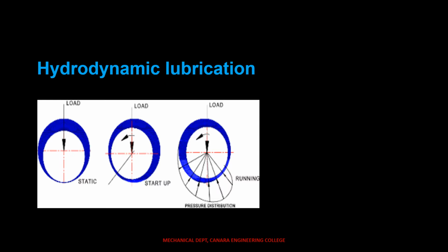Hydrodynamic lubrication does not depend upon the introduction of the lubricant under pressure, though that may occur, but it does not require the existence of adequate supply at all times. The film pressure is created by the moving surface itself pulling the lubricant into a wedge-shaped zone at a velocity sufficiently high to create the pressure necessary to separate the surfaces against the load on the bearing. Hydrodynamic lubrication is also called full film or fluid lubrication.